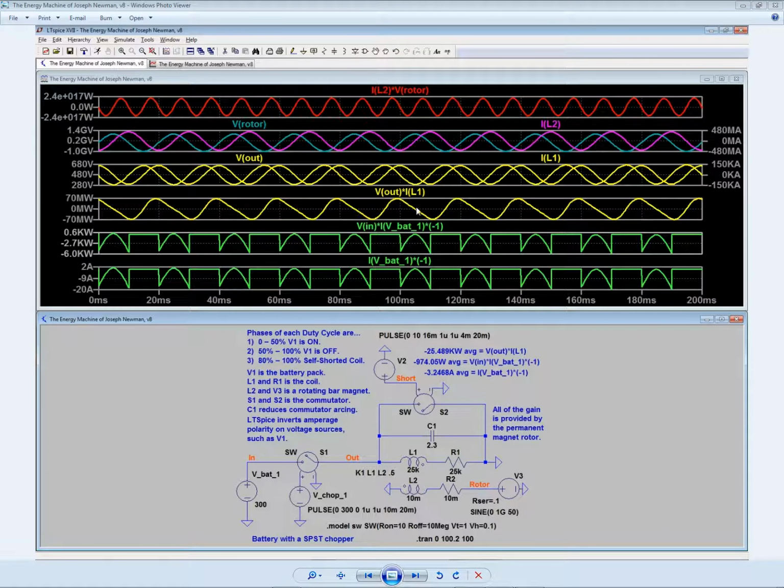It started to iron out, so it's less bumpy, less complex, and now it's just veering to the left, which means that the self-shorting of the coil is making it drop, I guess, in addition to the fact that the duty cycle is only 50%. So I think what happened here is we got an inversion, because normally the duty cycle would be a square wave here for 10 milliseconds and then drop. But instead we got it rising because it's going in the negative. See? So the whole thing became flipped.